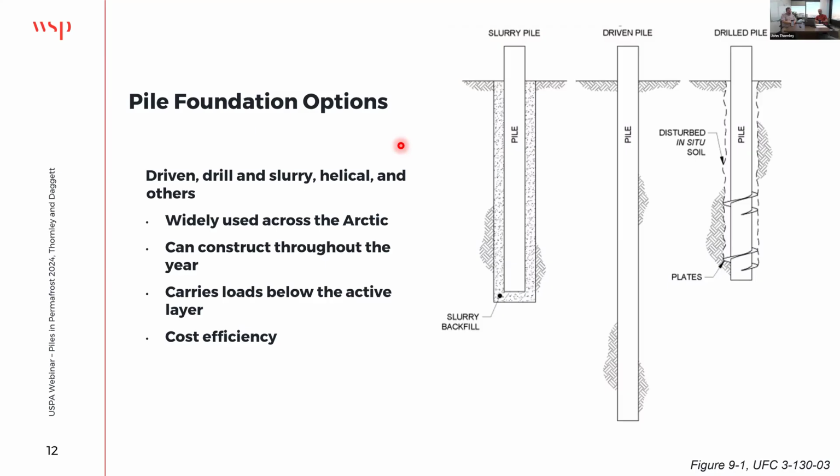It's very common to have wintertime construction, as well as summertime construction, depending on the location and the access to that site. Also, one of the things that these piles do is they carry the loads from those structures down below the active layer, where you have this seasonal freezing and thawing, year in, year out.